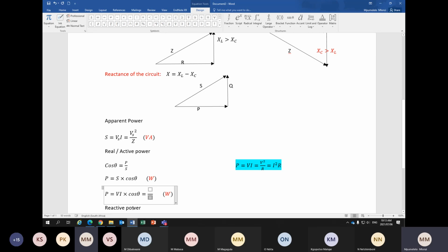We have the resistor, meaning we divide here by R. If you have a resistor, an inductor, and a capacitor connected in series, and you calculate the impedance of the circuit, it involves all those components connected in series and is represented by one parameter, the impedance. And across that parameter, you will have the supply voltage.